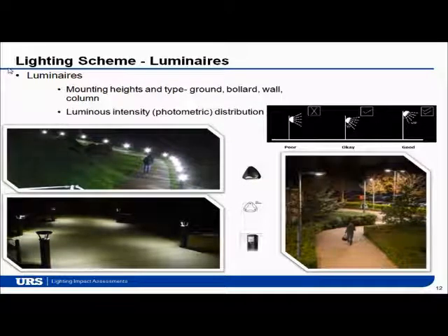Also, luminaires. There is a lot of choice and options on luminaires from many different manufacturers, as we've already heard yesterday. Mounting heights and that kind of thing, and also luminous intensity and distribution varies. We've now got a lot of options available to us that can actually mitigate the need for shields and cowls, because some of the fittings already incorporate optics to reduce backlight and have narrow distributions, etc.